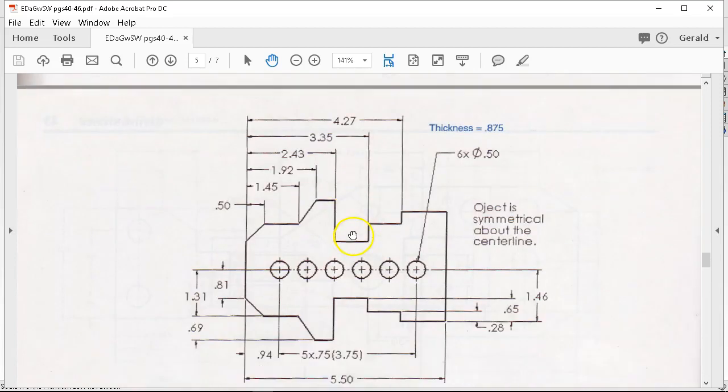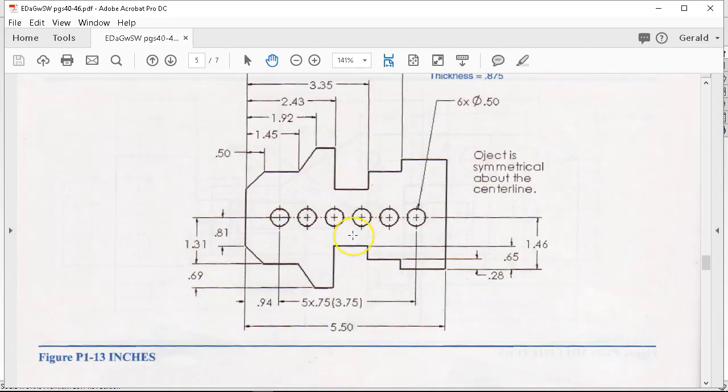All right. More pattern, more mirror. So most everybody that's gotten to this one has pretty much the same question. We draw half of this, and we're going to mirror it across the center line, so a good place for the origin is either on this end or this end. When you get to the circular, we're at another one of those linear patterns.